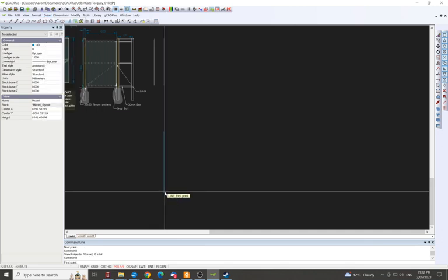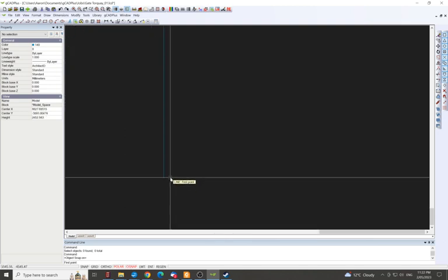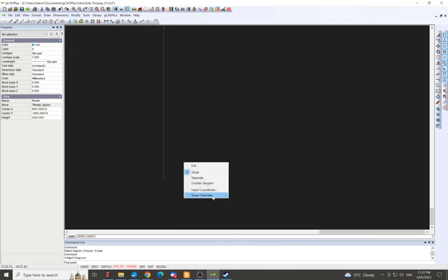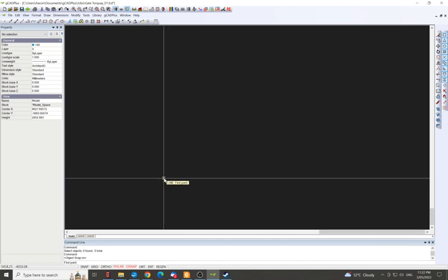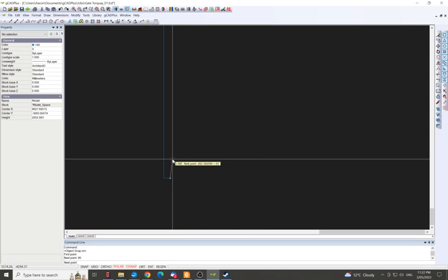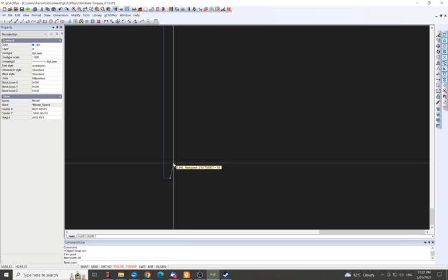Draw a line. We'll do another one there. Oh, we need object snap on, so that it clicks onto the corner. But all our settings are right. So snap overrides, everything's in there. Click that onto there. We're going to do this 90 mil. Then face the polar tracking up again, so it locks in. Not snaps, locks in. The only reason I say that is because I don't want to confuse object snap with polar tracking. So it's locking into the track. And this is 2400.